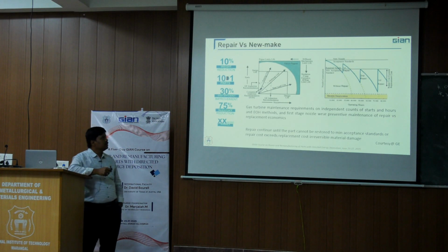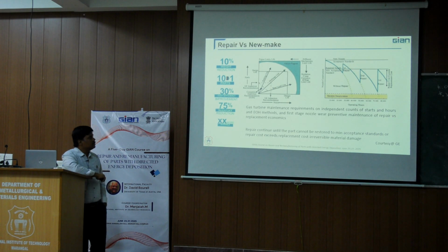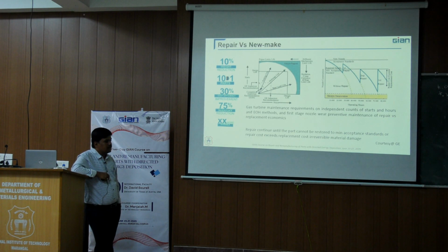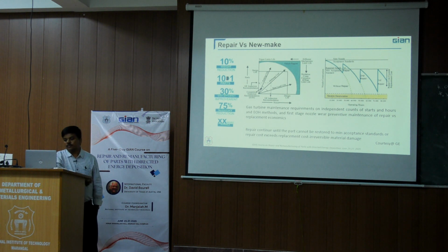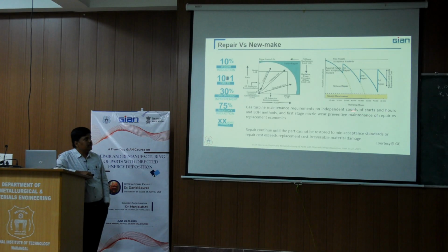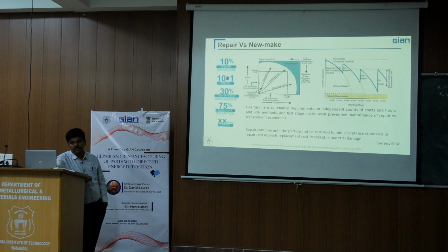If you see here, the gas turbine maintenance requirement is very high. It is dependent on the count of the start hours as well as what kind of methods have been maintained. For the first stage nozzle, we have preventive maintenance, repairs with respect to the replacement economics. If you see how much the nozzle has worn out after these gas turbines and all,